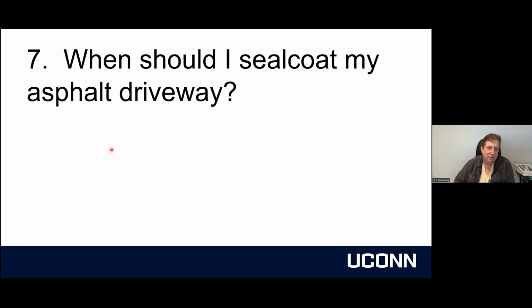Yeah, driveway sealing is not a bad thing to do. Usually the 4 to 5 year range is when you're going to get the most bang for your buck. If you wait too long, it makes it look good for a year until next winter, but it's really no more than painting the driveway black. It shouldn't be a repair. Its purpose is a sacrificial layer, so it'll preserve what's underneath it and help prevent water and air from getting into the pavement, for reasons we've already talked about.